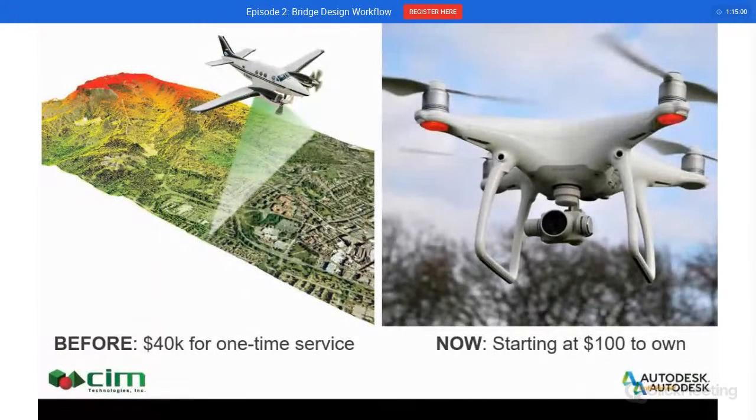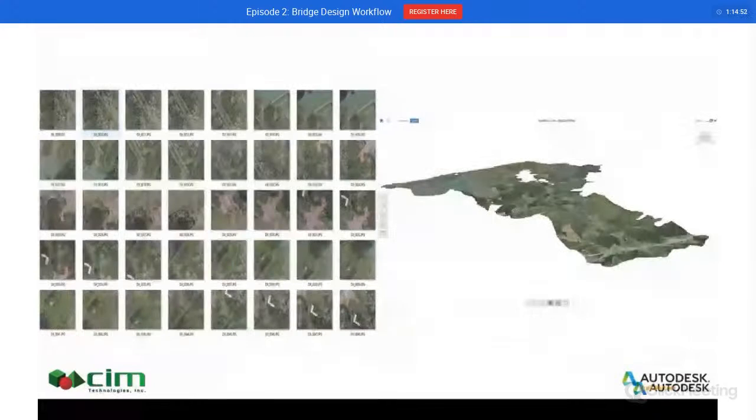However, now you can have your own drone for as low as 5,000 pesos or 100 US dollars. The concept is the same. The drone will capture hundreds of photos of that site, and then those photos will be stitched inside the software. The final output will be point cloud data of that topographic ground surface.